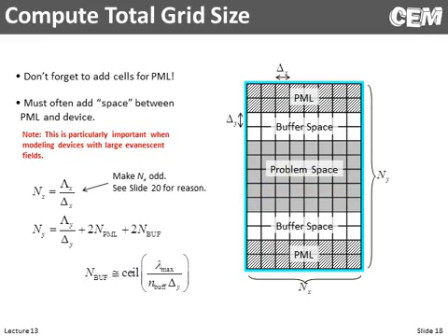So the number of cells wide the grid is needs to be an odd number. And that's because we want symmetry when we're calculating our spatial harmonics. We want to go from, let's say, -5 up to +5 and passing through 0. So that would be 11 points. And I can make that argument. So if we have an even number, then we cannot pass through 0 and have an even number of spatial harmonics on the negative and positive side. Now, it is absolutely possible to write a code that can handle an even number of points, but I think it's just simpler to just make it odd.